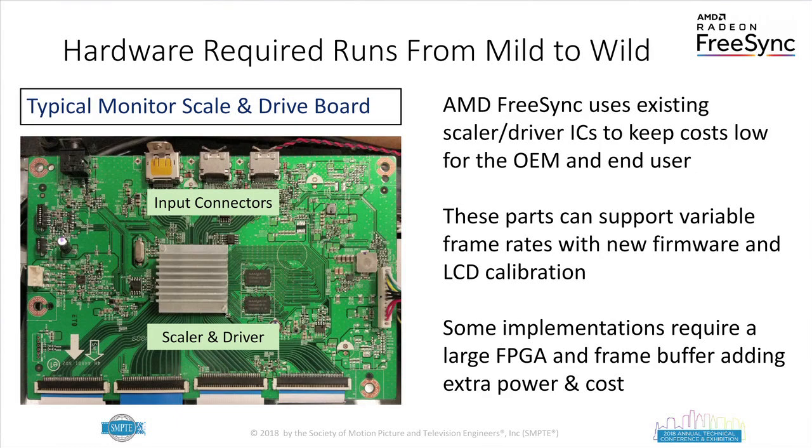This is the inside of a very typical monitor. There's HDMI and DisplayPort connectors at the top. Under the heatsink, there's a little scalar controller chip. And at the bottom, there's the connections out to the actual raw panel. Those little scalar controllers are actually fairly powerful. They have a micro, they have a lot of counter timers. They do all the lookup work for the overdrive. They have a little bit of a frame buffer for that.